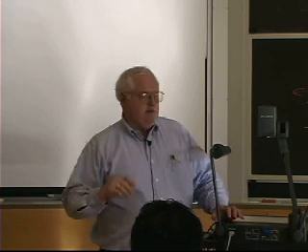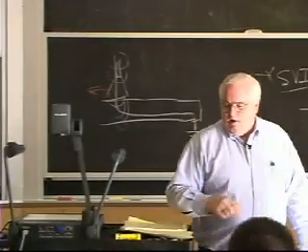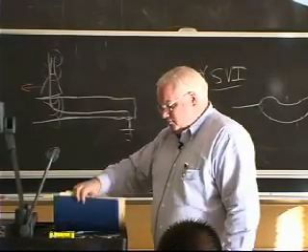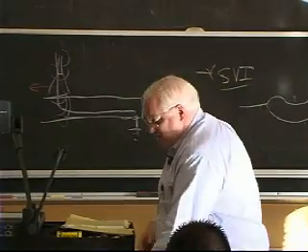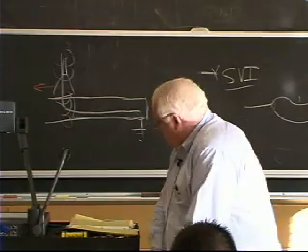So one of the problems with steel sometimes, and HY130 has this because it's a high nickel steel and it's easily magnetized, is that the steel can magnetize itself and generate enough magnetic field that you can't weld. I remember once at David Taylor, I was down there one summer, and the welders had been trying for several weeks to weld this one HY130 plate.